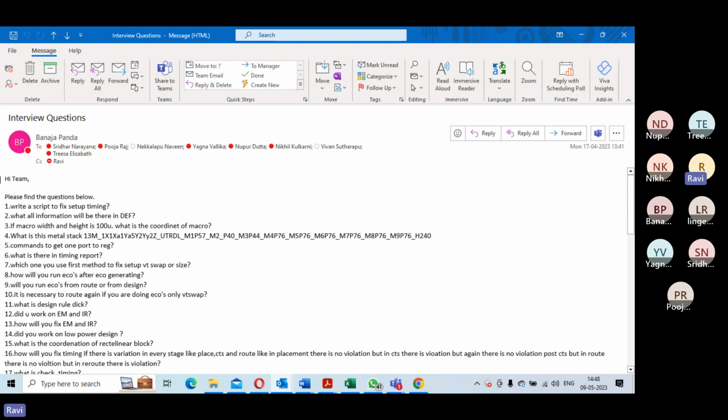Okay. Number 8, then what you will do is you will look at swapping, or if it's congested, then swapping will take a priority over a lot of your upsizes, because if you just go and upsize, then there's a problem in that area, you could cause DRC issue. So then you will look at upsizing, because upsize doesn't cost you anything on the route.